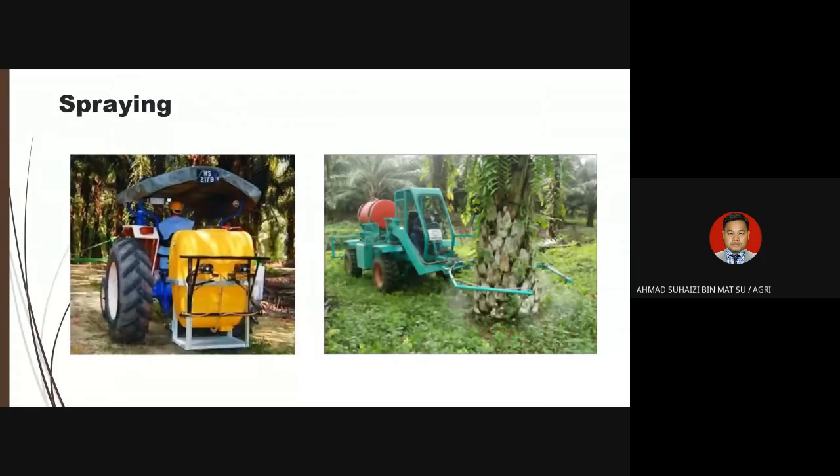Yeah, and then also for the spraying of pesticide, typically, if you remember, we did the spraying, did we not? Yeah, spraying activities. So this is the typical boom sprayer that we are going to use. Sometimes people have a split system, not using the PTO, but an independent engine system for the boom sprayer, and then deliver the spraying manually across the area.